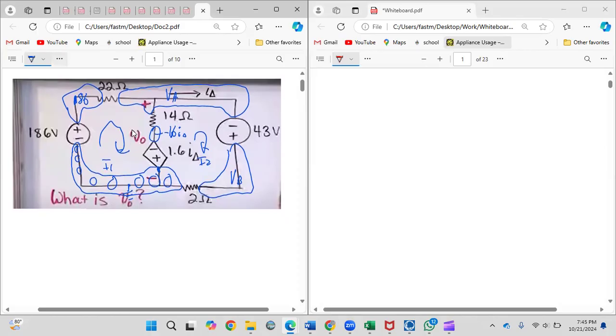So I run through the nodal, same steps I showed you last week. It ain't gonna change. So after you label your reference, you draw in your nodes, you draw the voltage of nodes that you know the voltage for, you analyze your circuit. The next thing I have to do, since I use nodal, is open my eyes and look to see if I have any supernodes.